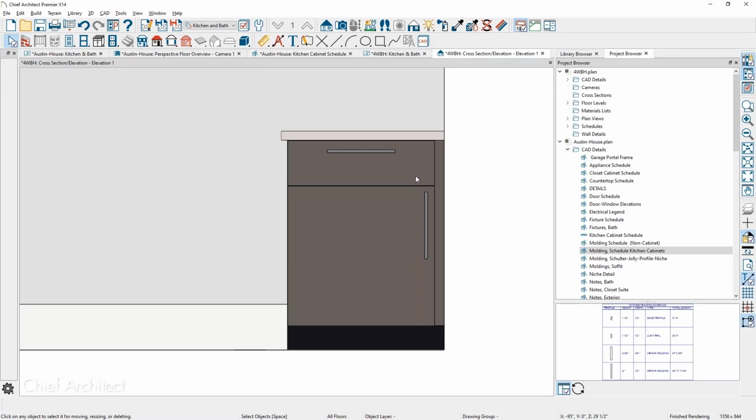So just so I know, when you order that cabinet, do you order it as a 1.5 extended style, or do you get it with a 3-inch or a 5-inch and then shave it? I usually will order it with a 2-inch or 2.5-inch extended style, and I'll let the contractor scribe it to my specifications. I have very specific measurements that I like to see on the CAD plan, so he knows he's scribing it to 2 inches, or if that wall's out, he knows he's got to scribe from 2 to like 1 3/4. Yeah, got it.